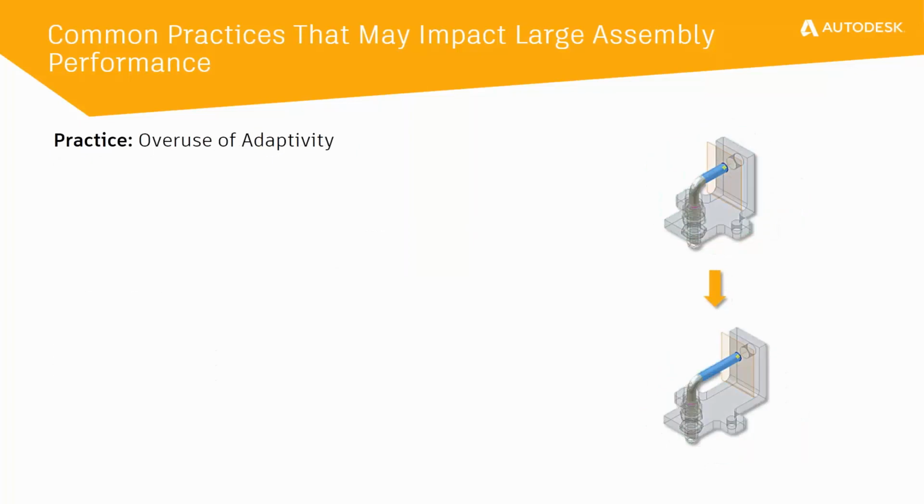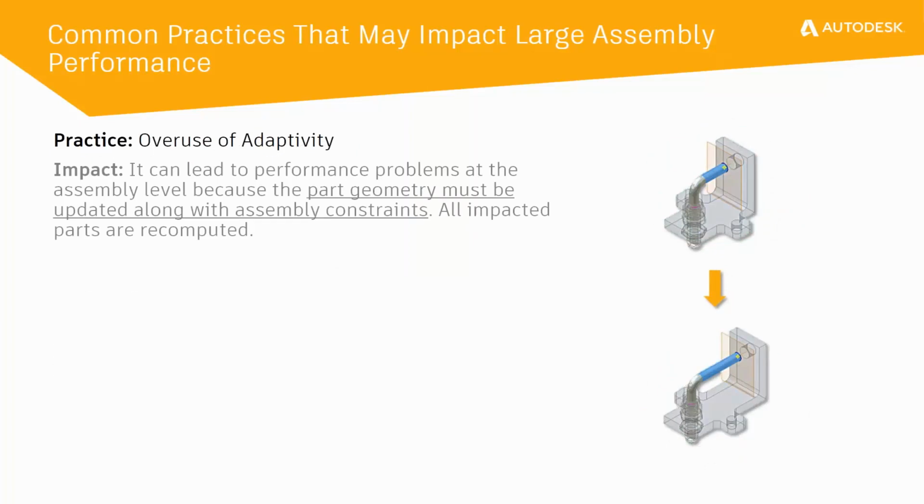What about the overuse of adaptivity? Now this can lead to problems because the part geometry must be updated along with the assembly constraints, and this really impacts you because all of the parts essentially are being recomputed.